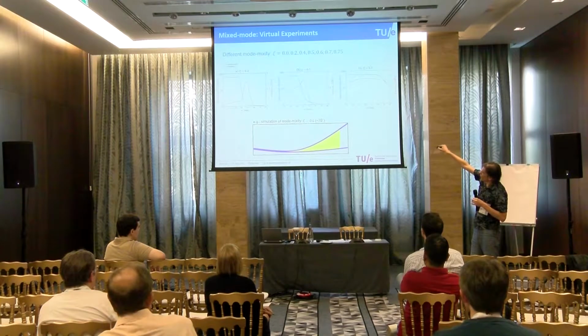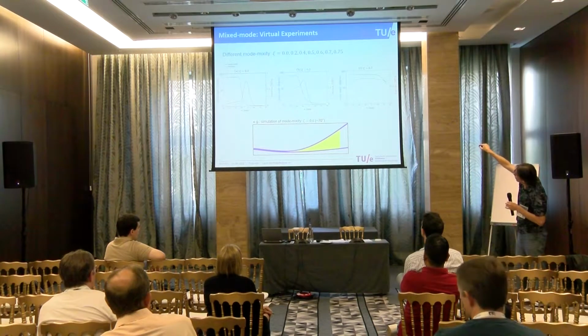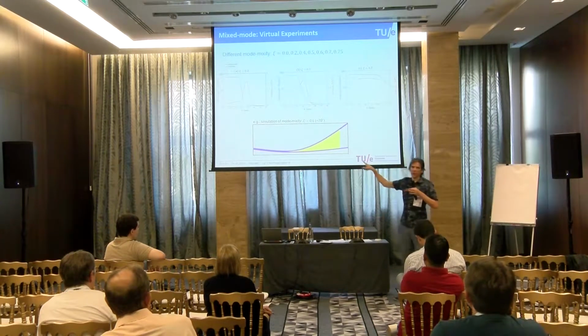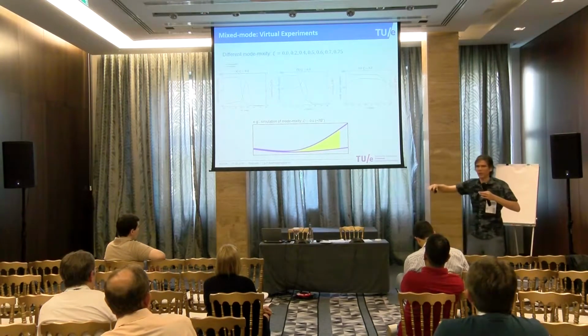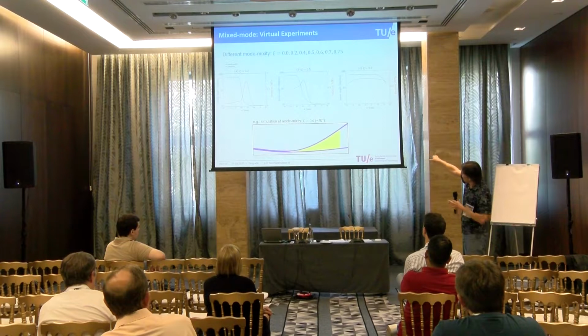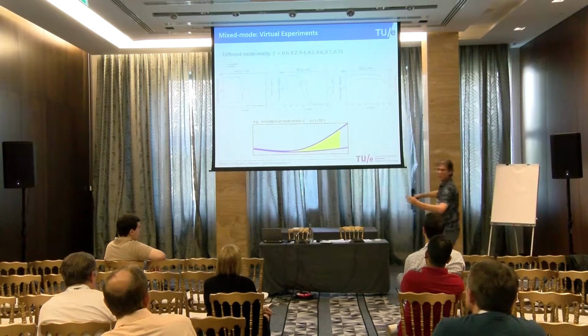So this is for a test that's close to mode 1. This is close to mode 2, and this is intermediate. But what's interesting, the blue ones, is the angle. So you can see that even though this test was designed to be constant mode mixity, the mode mixity changes rapidly. So while you go from right to left, basically the angle is rotating over which is being pulled.